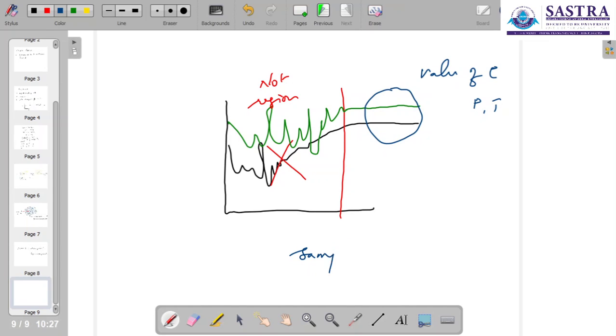So that means our sample volume, right? Our sample volume needs to be in this part, so there is a critical sample volume below which we don't want to report any property. I showed examples of temperature, pressure and density, but this is in principle applicable to any variable. This is the central crux of the continuum.